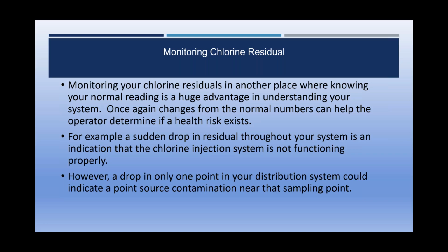so that you can look at that and determine whether or not you're running enough chlorine into your system. In fact, often when you start a brand new system up, you do a calculation, which I'm not going to get into, but it's not too difficult to figure out roughly how much chlorine you'll need in your water to give you the recommended 0.2 milligrams per liter of chlorine. In most systems that's pretty straightforward, but depending on the chemical composition of the water, that can change.